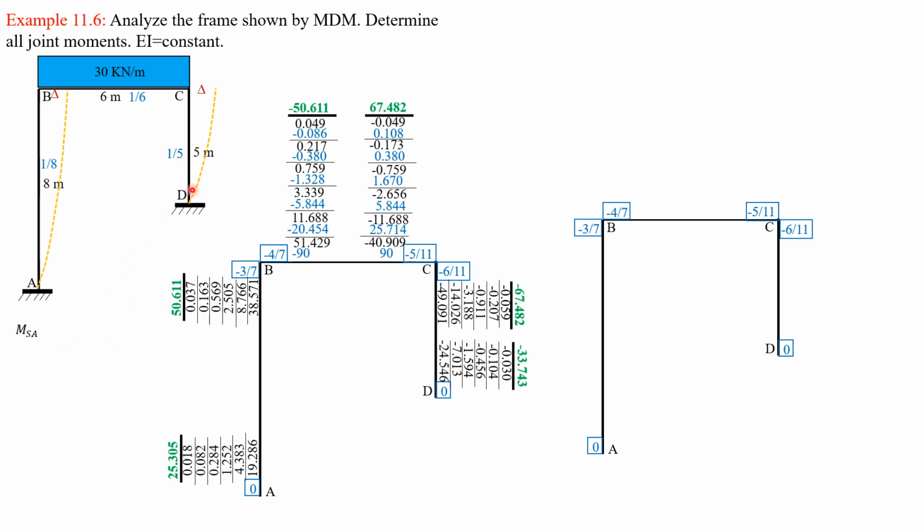Then the moment due to side sway in CD is negative 6EI delta over 5 square, and I assume it is equal to negative 64. Remember the numerator is constant, negative 6EI delta, you may imagine that is 1.